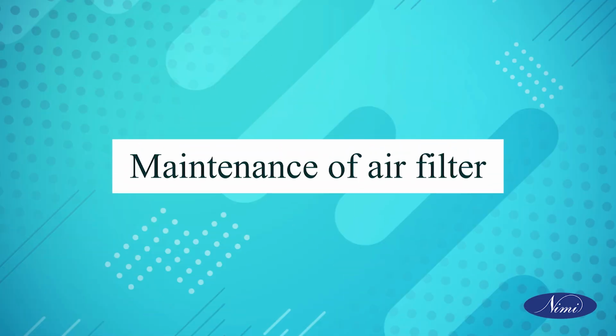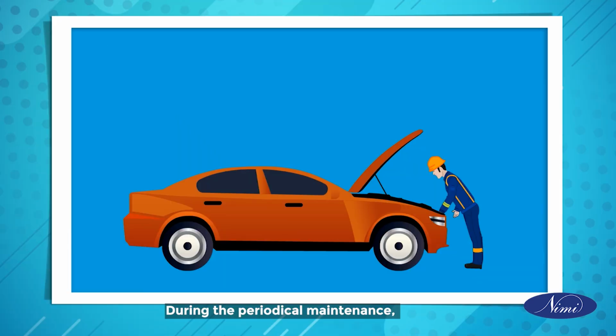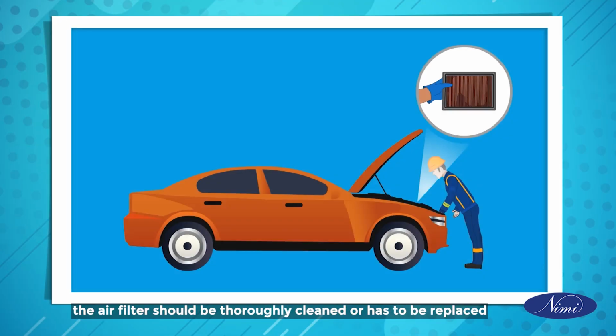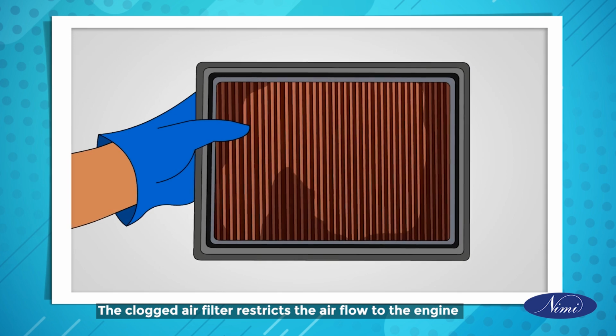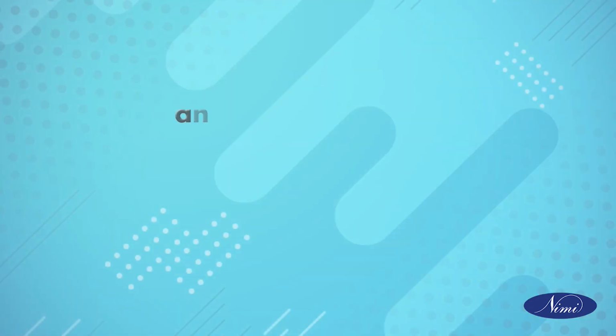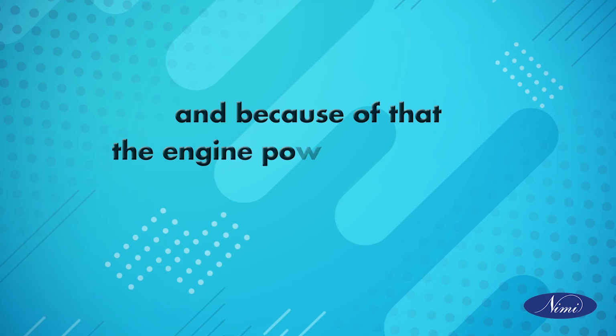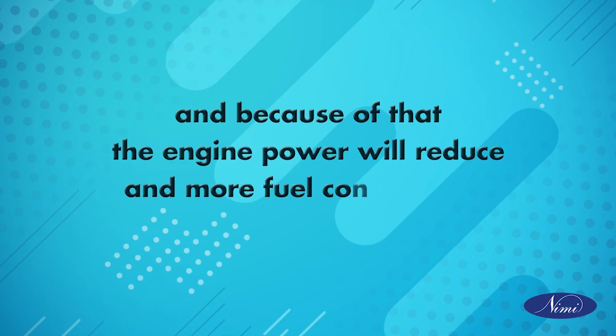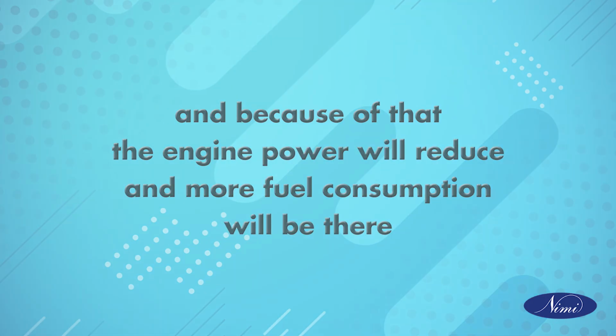Maintenance of air filter. During periodical maintenance, the air filter should be thoroughly cleaned or replaced. A clogged air filter restricts the airflow to the engine, and because of that, the engine power will reduce and there will be more fuel consumption.